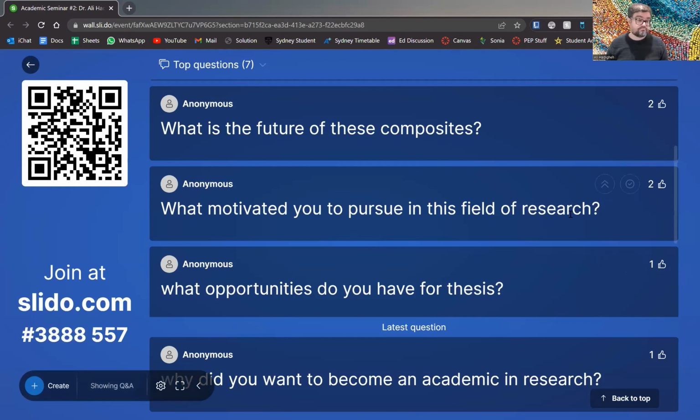In turbine blades, obviously, they are mostly made of FRP materials. They are mostly made of glass fiber composites. Interesting. If you are specifically asking about construction, for construction, we use these materials as rebar. Instead of having a steel rebar, we can have glass rebar or carbon rebar, mostly glass rebar and a fiberglass rebar. They are very durable against harsh environment. They are mainly used in concrete and replace the steel rebar in concrete in marine environment. Or even for pedestrian bridges or different types of bridges, they use these composite materials.